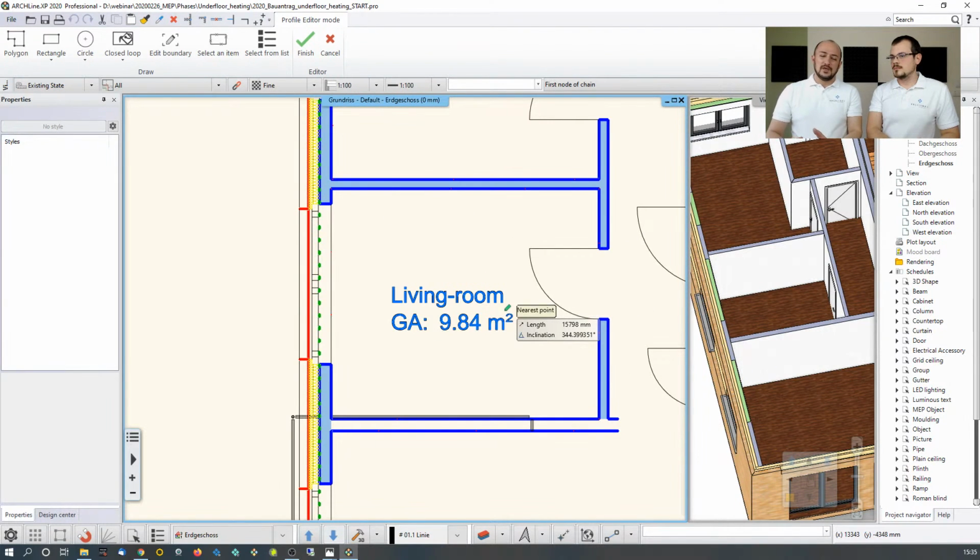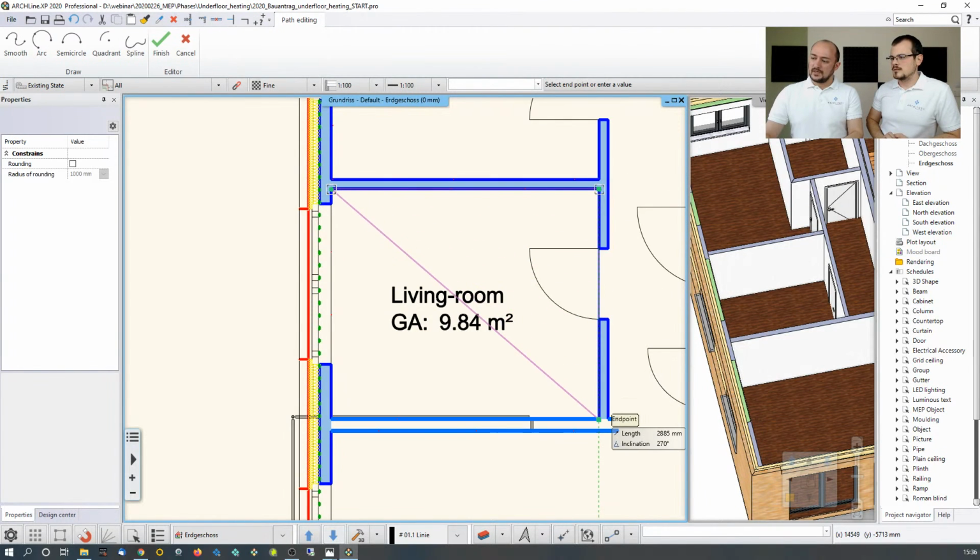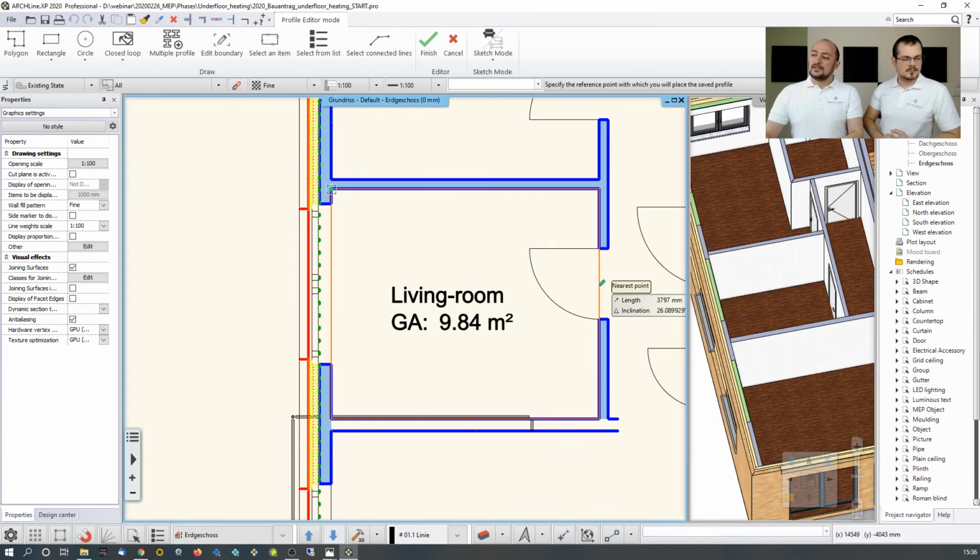It is similar to when you create the polygonal room stamp. Yes. But now it's not necessarily connected to one room, so you need to find the contour where you would like to place this. So you can just click and say, okay, this is the contour, and this is a simple rectangular part. And then you need to set where this piping steps into the room. Now it's mostly through real openings like doors in between the different rooms. So I will just tell the software it enters from here.